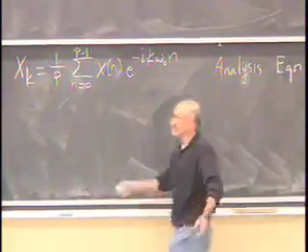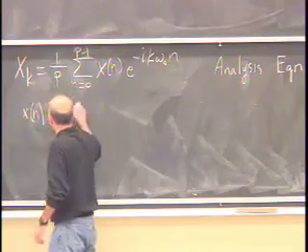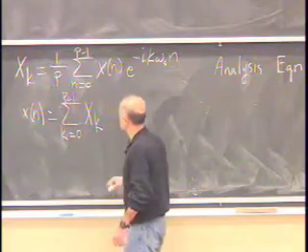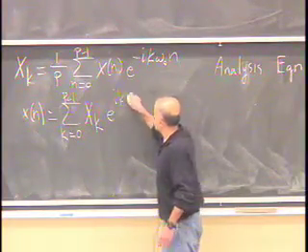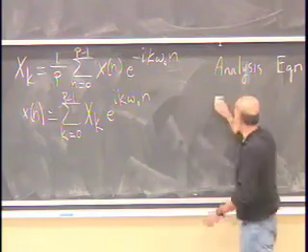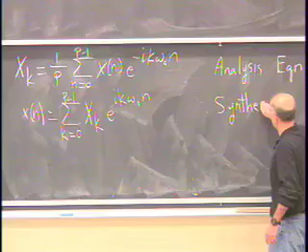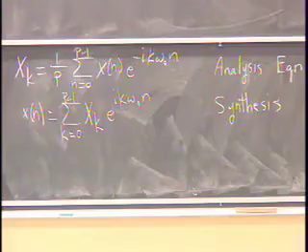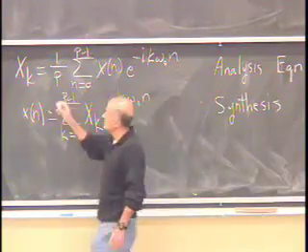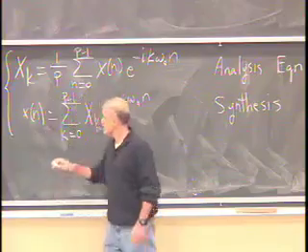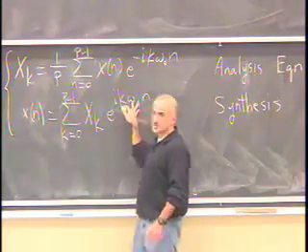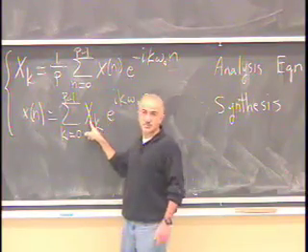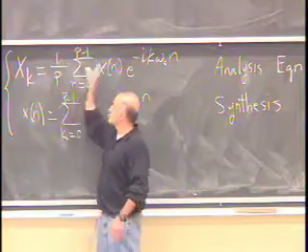So we've actually got our two equations. x of n equals a linear combination, where that linear combination goes from 0 to p minus 1, of these complex exponentials: the synthesis equation. And the top equation is the analysis equation. That's all there is to the discrete Fourier series story. You say x is expanded in terms of complex exponentials, if you can, and to do that, you need to find the coefficients. Can you find the coefficients? Yes, with this equation.